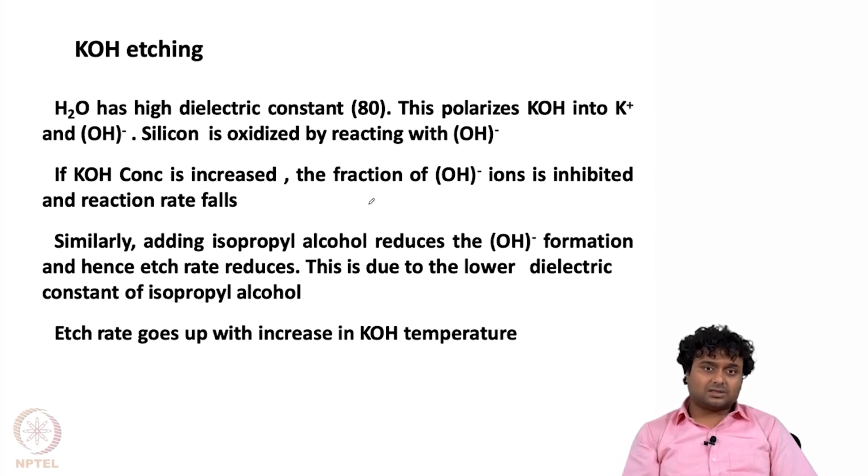So in that case the surface will be etched very fast, and it will be a little bit rough. But later on we can use an even higher etching rate, or you can use IPA to reduce the etching rate, and accordingly we can generate smooth surfaces. So the final surface will be much smoother, and also we can finish the process faster.